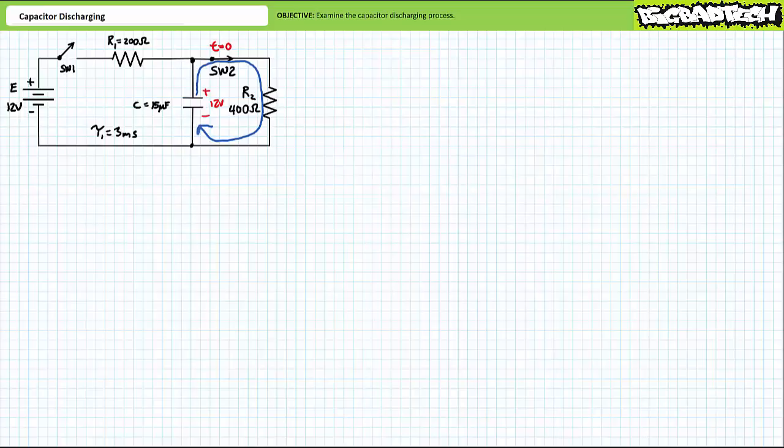I'll come back to correct this assumption after we're complete, and compare and contrast the charge and discharge process with one another. A couple events define the discharge process. Number 1. The quantity of charged particles accumulated on the capacitor plates during the charging process seek equalization through this new discharge path afforded them. Conventional current leaves the capacitor, emanating from the positive terminal, traveling through the 400 ohm resistor top to bottom, and returning via the negative terminal.